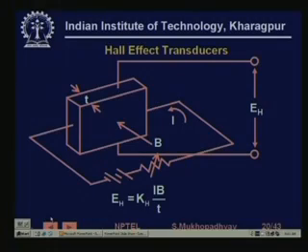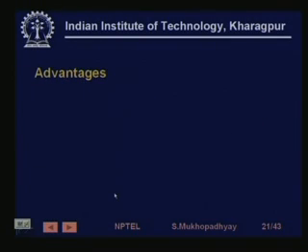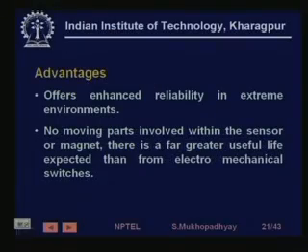Hall effect sensors are used for various reasons. One of the main reasons is that it is very reliable. No contact is required, it is a non-contact environment, and there is no moving part in the sensor.